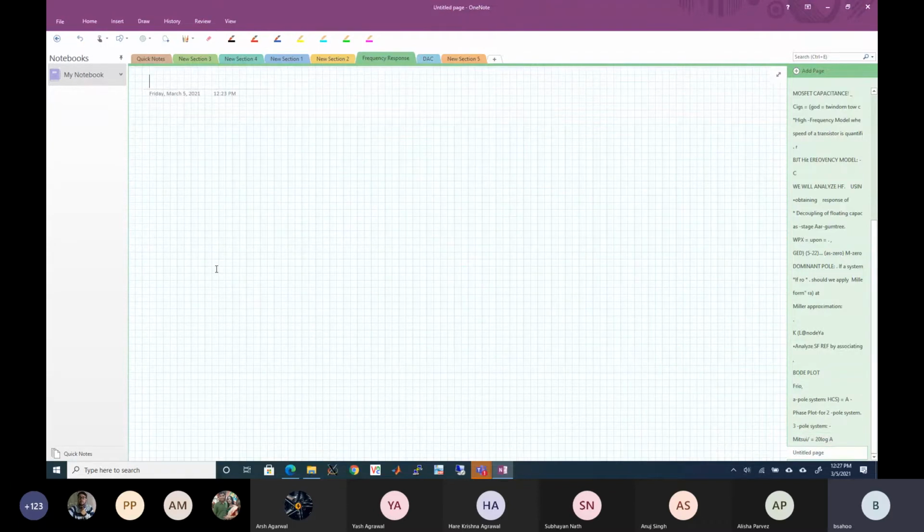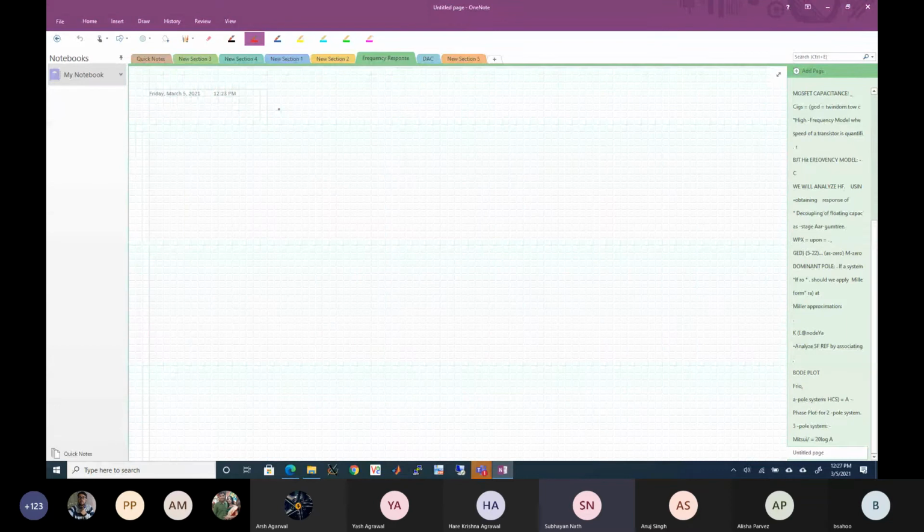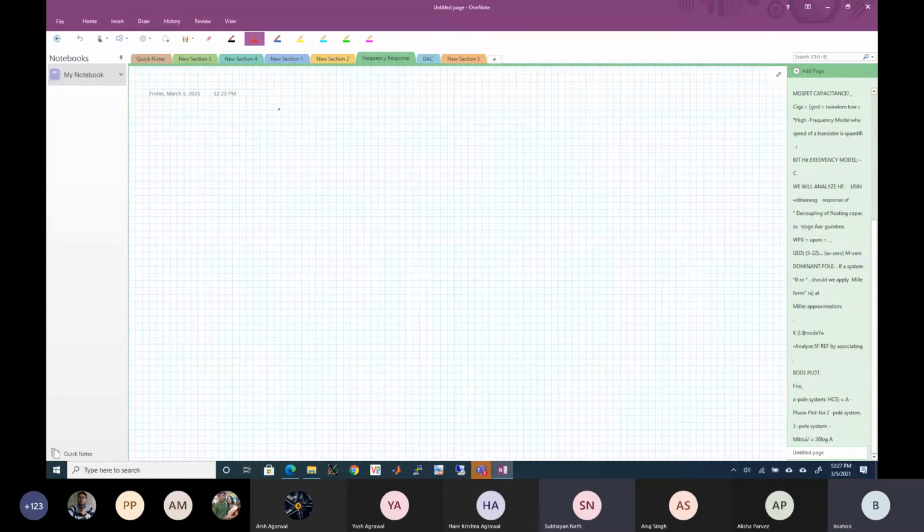Okay, so now we have seen. Now let us see what happens. Sir, if two poles coincide, then there is a roll off of minus 6 dB. No, roll off of minus 40 dB per decade. I was saying about the roll off. I mean minus 6 dB at that point, yes, it will be minus 6 dB down from the DC value. Yes, but we usually define the cutoff frequency as minus 3 dB.